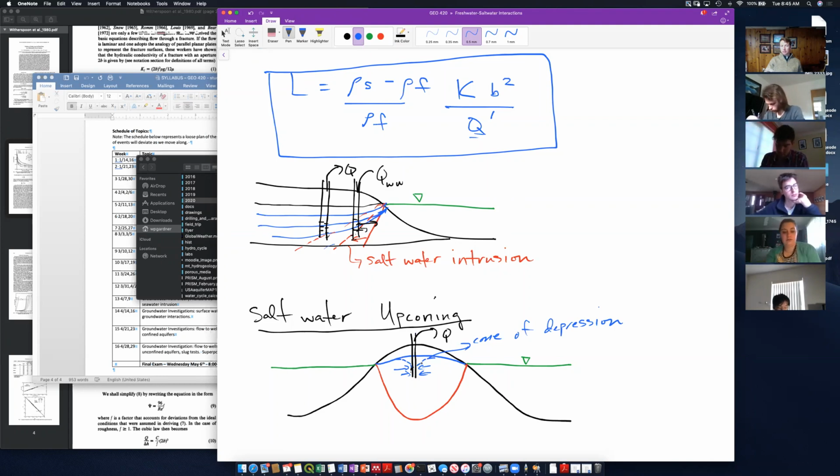All right. And the shape of this cone of depression, and how rapidly it sort of propagates out into the aquifer, we're going to talk a lot about, because that's a principal way we investigate the properties of the aquifer, is to look at how this cone of depression forms and how it changes as a function of the pumping rate.